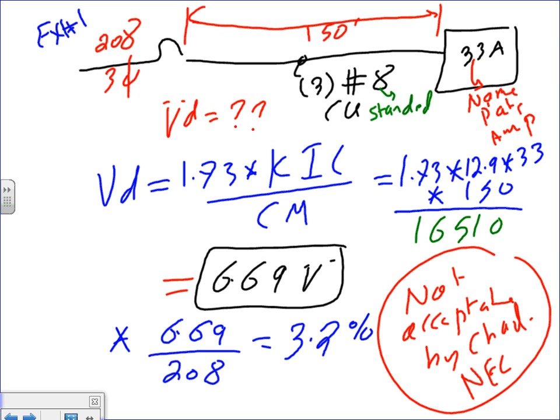Here's my question for you, buddies. You're the engineer, you're going to resize this. I'm going to size a conductor that can actually meet the code. The answer would be easily to go higher. What's higher than 8? Let's go to 6. But let's do the calculation and see how much it would take to correct this problem. I need to keep it below 3.